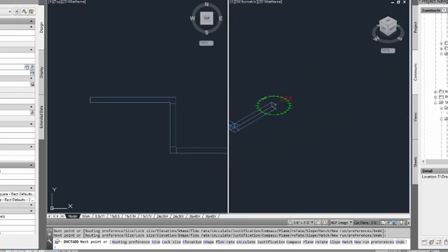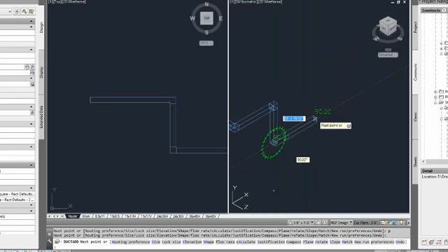But if I come down here again and I look at next to the compass, there is a command called plane, or if I just hit the P key for plane, you can see that my compass changes its plane. I'm now drawing in the front view, and when I go to route an elbow, it'll actually rotate that elbow up or down or sideways in the front plane.